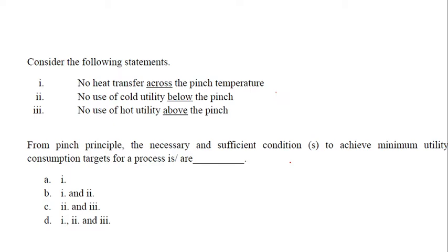So I am writing here the necessary conditions to achieve minimum utility. First condition is no heat transfer across the pinch temperature.